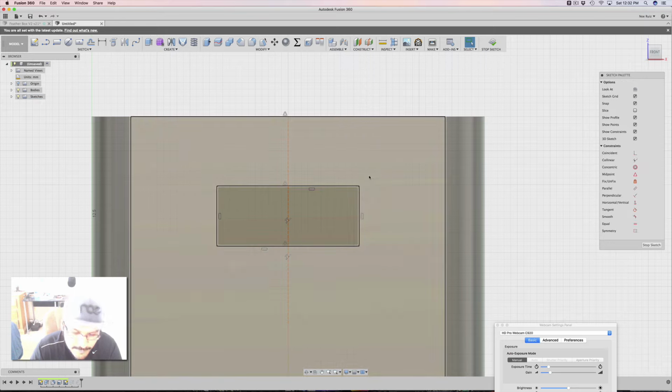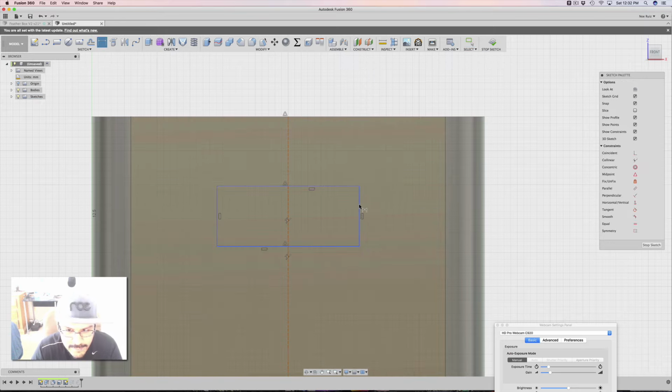So the next thing I'm going to do is assign some sketch dimensions to this thing just to flesh it out. So I'm going to click on this edge here. It's got some weird numbers, so I'm just going to make it 2. And then this width right here, instead of putting an actual value, I'm going to use a little bit of math. So I'm going to say I want the length to be divided by 2, right? So length divided by 2. Now it's giving me a value of 15. And what's cool about this is that because I'm using the actual length user parameter, it'll always update whenever I update the length, which is kind of cool.